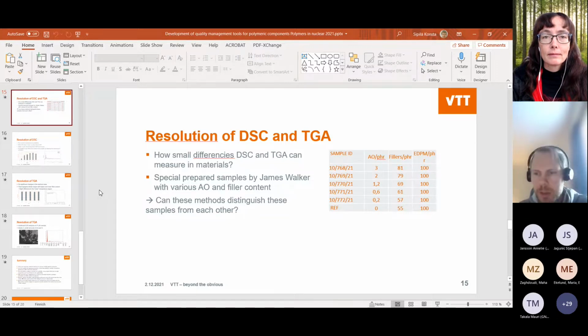Some of the colorants act also as photo stabilizers, so they protect the polymer from UV aging. And I remember discussing with Sue Burnett on this topic as well. If I remember correctly, she said that some of the colorants may also have a role in the oxidation of the polymer, so they may have an effect on the aging of the polymer.